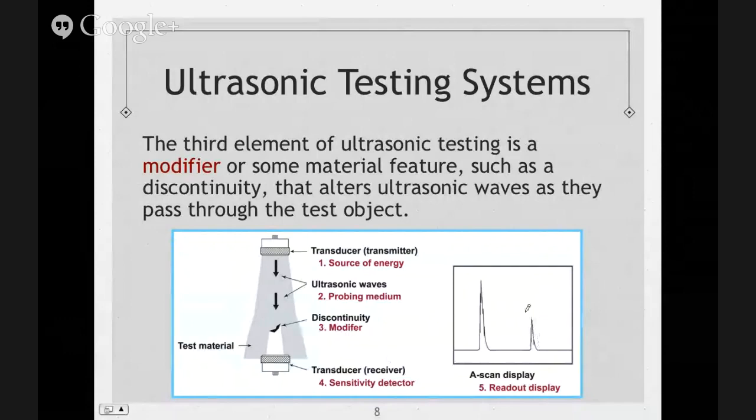If this is what you see and it's below your 40 threshold, you'll just go ahead and reject that part based on the inspection criteria. Now, if this indication gave you 50%, this is your 40 line, and this would be your 50%. Your inspection criteria told you that anything below 40 is bad, and you get 50, so in that case your part is not rejectable. You'll make a note of it, but that part can still be in use.